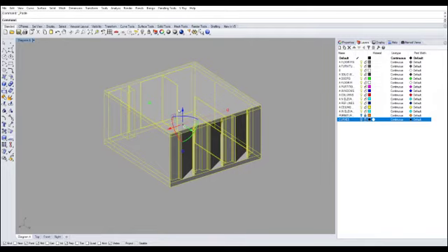So to differentiate our duplicate model from the original model, I want you to go to the Layer tab. I want you to go to New Layer to create a new layer. Let's call this Diagram B. And then right-click that Diagram B and then say Change Object Layer. The new duplicate object, or simply it could be the original model, has gone to the Diagram B layer. To double check that, I'm going to hide the Diagram B layer.